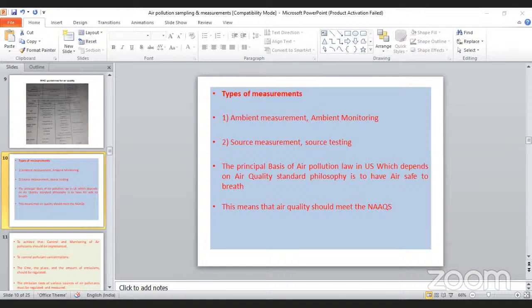There is one inlet and one outlet. Through the inlet, the sample enters the solvent, and the sample is collected and dissolved in the solvent or water which is present in the bottle. The remaining insoluble gases exit from the first bottle, and similarly, similar bottles are arranged in a sequence, 4 or 5 bottles. Those bottles are arranged in a cooling medium, either an ice bath or water bath, because all these gaseous pollutants are mostly released at a little higher temperature only.